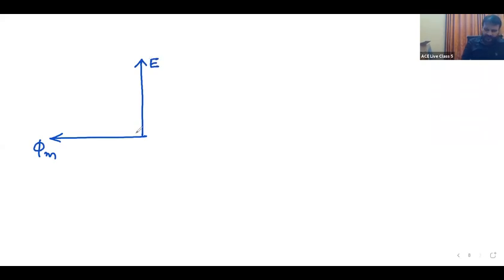That E is the same for the generator and the motor. For the generator it is EG; for the motor it is the back EMF, EB. Red color I am writing EB. But EG is on the quadrature axis, and EB is also the same. The induced EMF equation is the same for generator and motor. For the generator we call it generator EMF, for the motor we call it back EMF. Both are the same.